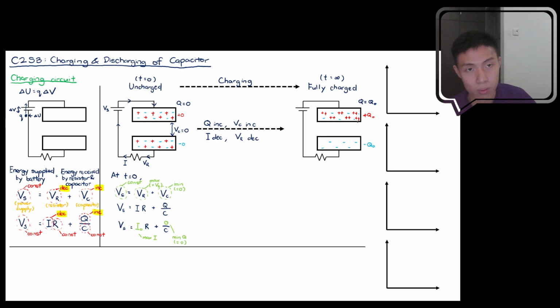If you look at the potential difference across the capacitor, V is equal to Q over C, right? If your Q reaches maximum, your VC should also reach its maximum. So VC maximum is called V naught C, peak. This is still the same old VS, nothing has changed. But the voltage across the resistance later we know will drop, until maybe 0. So the current over here will also decrease as well, based on what we have discussed just now.